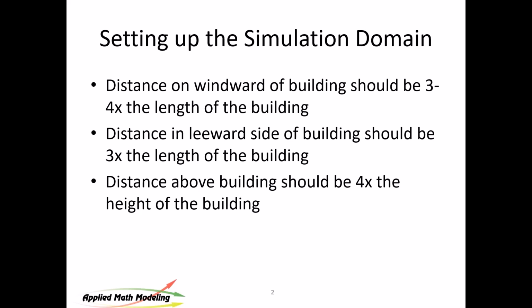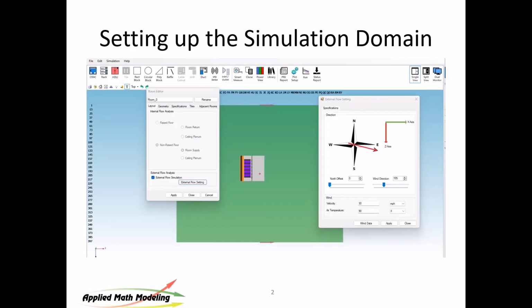because we've got to resolve the mesh. The cells, remember, we break the volume up into, in this case, hexes, three-dimensional hexahedras, and then we solve the conservation of mass, momentum, and energy on each surface and interpolate it across the cell, and we have to converge it to an accuracy of typically 10 to the minus fourth. So we're looking for good resolution, and to do that, you need enough size to do it. And then on the top, 3 to 4 times the height of the building, okay, because it is a three-dimensional block.